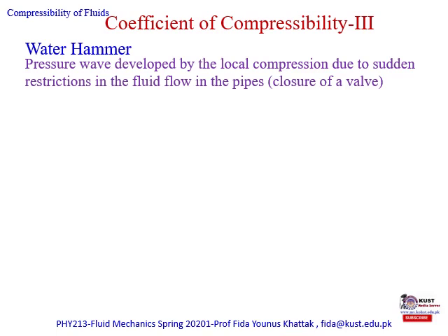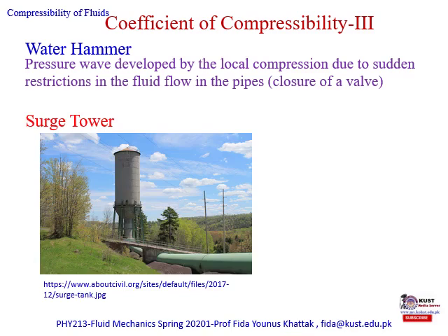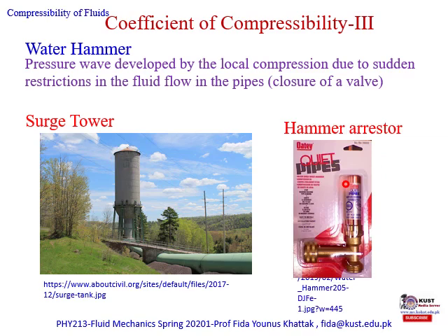In order to overcome the damaging effect of this water hammer phenomenon on the pipeline, a surge tower is usually deployed that has an open surface in the tower that works as a shock absorber. On a smaller scale, usually a hammer arrestor is installed that takes care of the water hammer phenomenon.